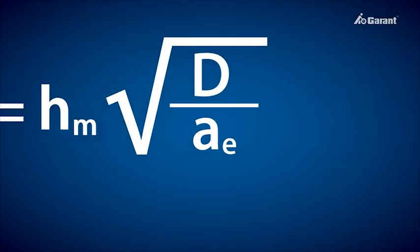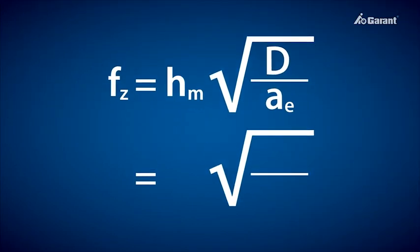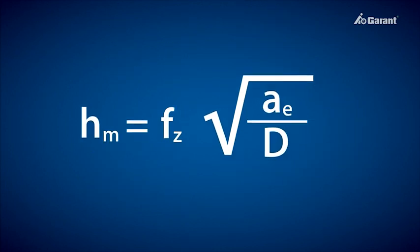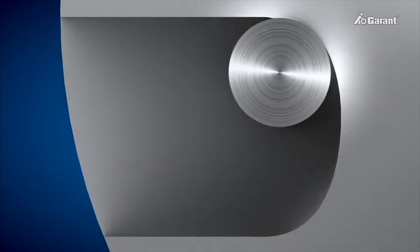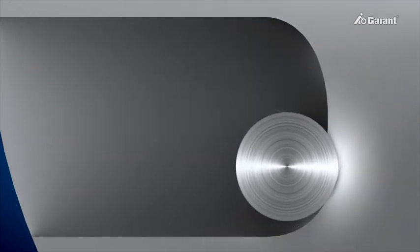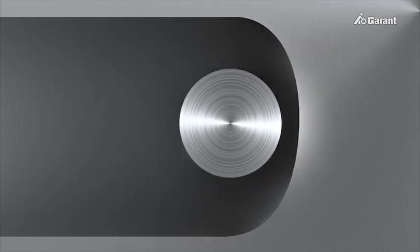Because of the variability of AE, we can now revise the formula as follows. So, from now on, it's the average chip thickness hm that is constant. Modern CAM systems and controllers now use the constant value of the average chip thickness, that is hm, to calculate and control the optimum milling path, thus ensuring maximum machining efficiency.